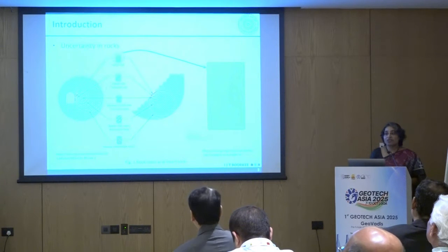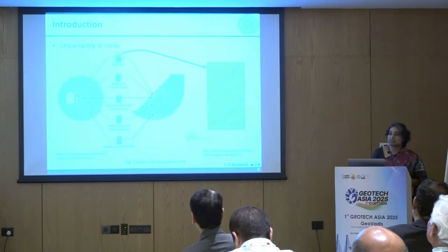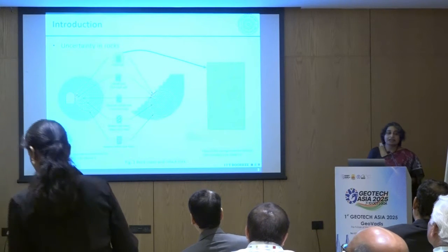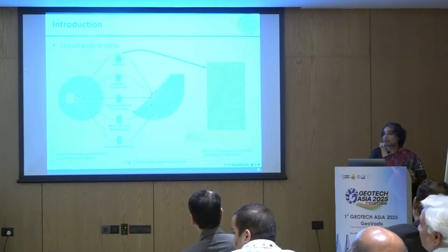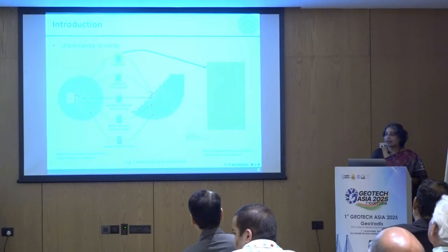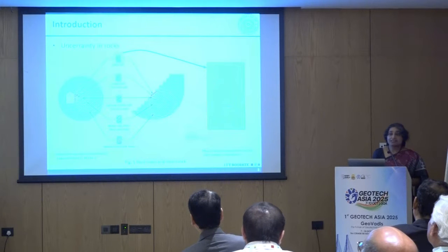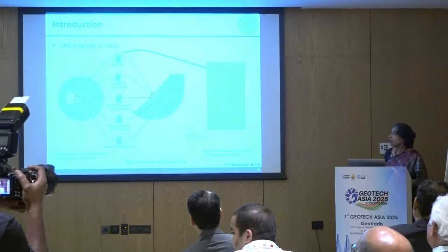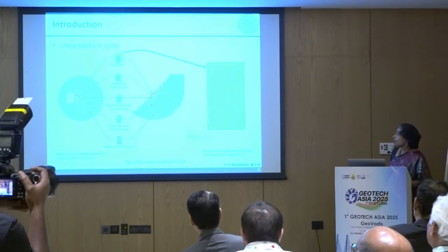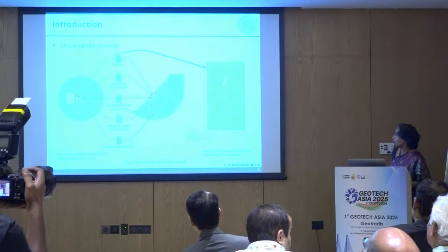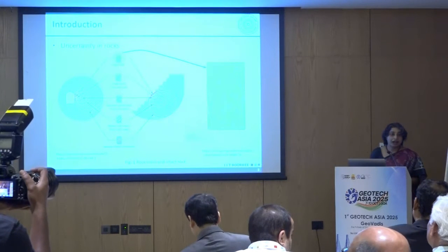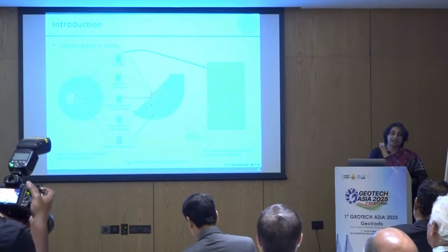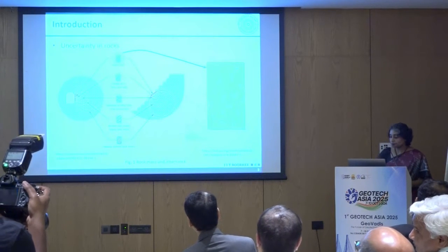So what happens is, when the mechanical characterization, which is usually done on the intact rock in the lab, is done, let us say you conduct 50 tests, you will never get a single value of, say, UCS or the triaxial characteristics. So this causes our material to become uncertain or random, which really cannot be handled by our conventional way of analysis, which is deterministic.